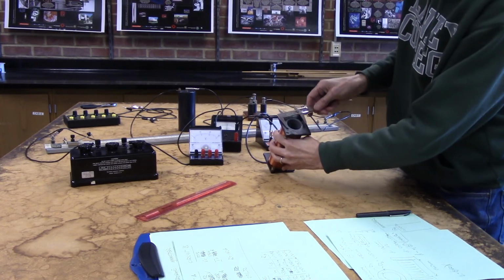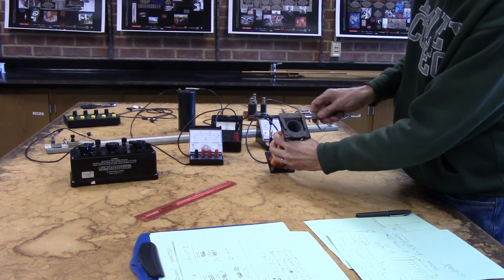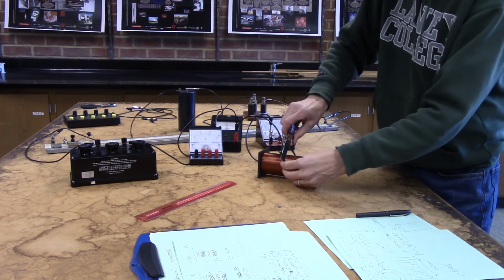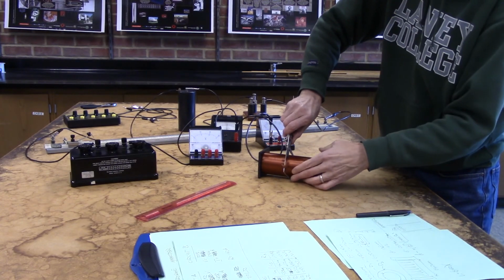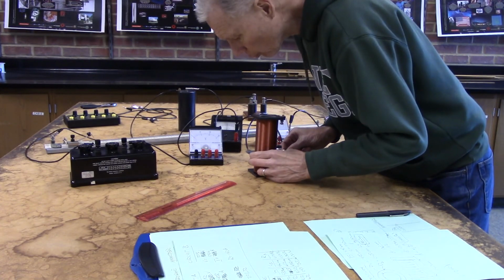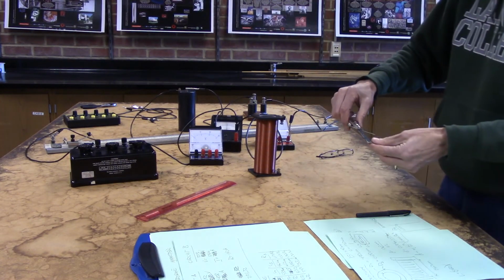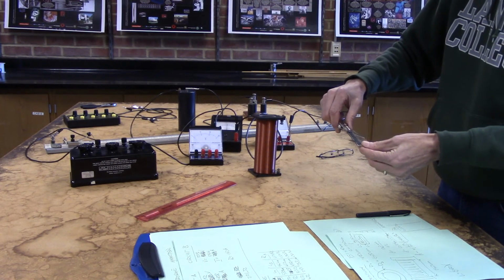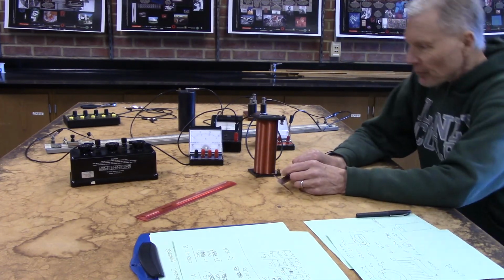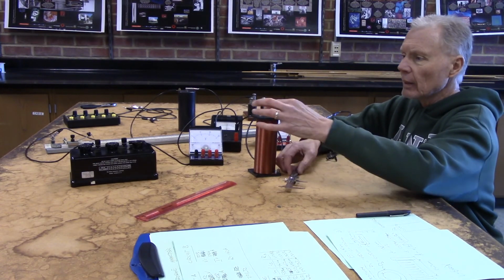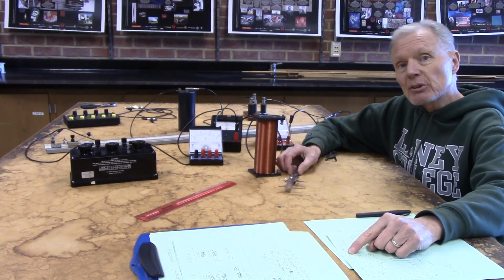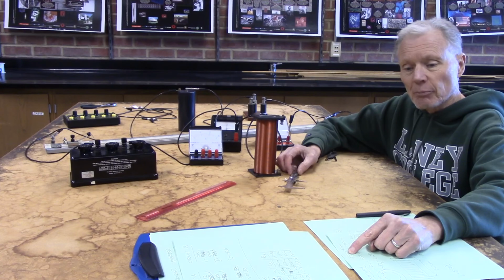So I'm getting 4.8 centimeters for the inside of the wiring, and then the outside of the wiring I can access from here. And so as far as looking at the outside of the wiring, I want to make sure that the calipers reach to the center. They do. And the caliper readings on this came in right at 6 centimeters. So I've got inside surface at 4.8, outside at 6. The average value for the diameter is 5.4.